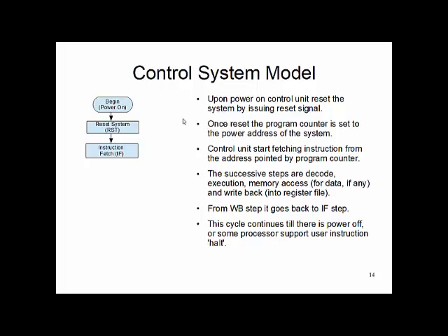If you look at the hardware specification, it tells you what the program counter value is set to when you first power on. It's different for different processors and definitely doesn't start from 0000. It is a predefined value. All right, so that's called the power on value of the program counter.